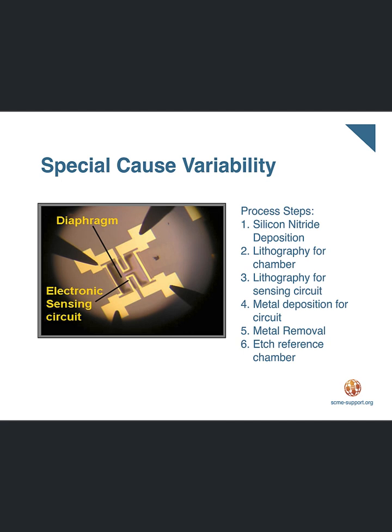For example, in the coat process of the photolithography step, it is desirable to have a specific thickness of photoresist. The resulting thickness depends upon, or is a function of, the spin speed of the chuck on which the wafer sits, and the actual viscosity of the photoresist deposited on the wafer's surface.